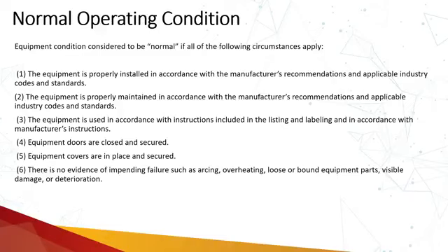So all the equipment doors are closed and secure. There are no doors open when I am interacting with those particular equipment. Equipment covers are in place, the back plate or the front covers are in place. So there is no chance of any rodent or any other external animal, like rats or cats, entering the electrical equipment, and when I am operating that equipment, it might cause a flashover.